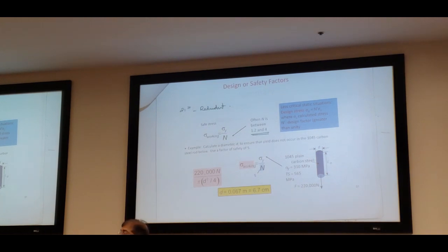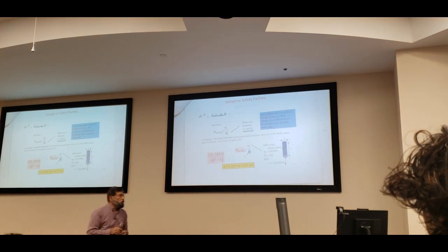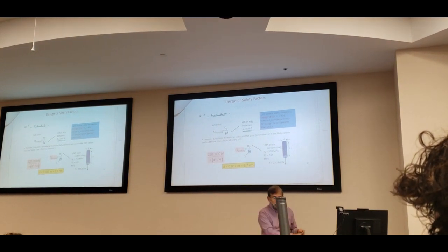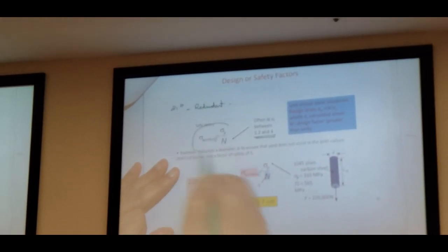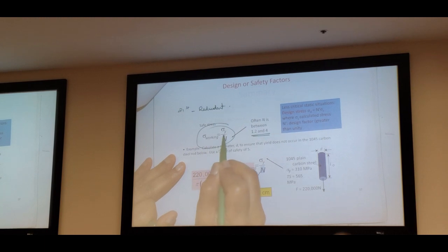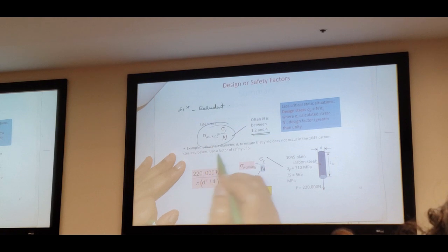on top of it, you need to have a redundant structure, which means even if one structure fails, the critical components, the second one should withstand whatever that load is. That's the approach. So from the stress, the general equation is this one: the working stress is sigma y over n. We still use that 20th century approach.